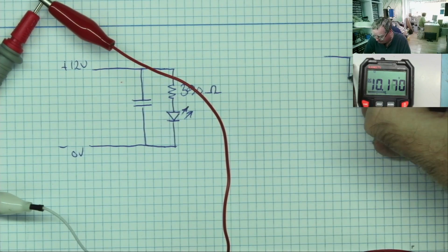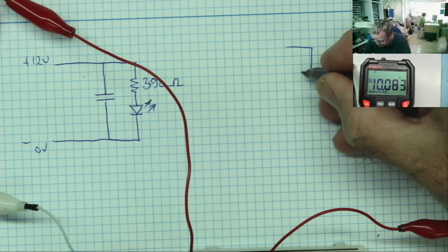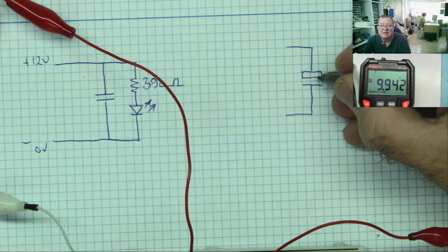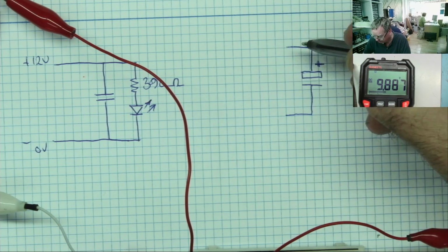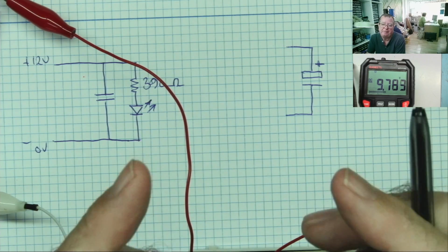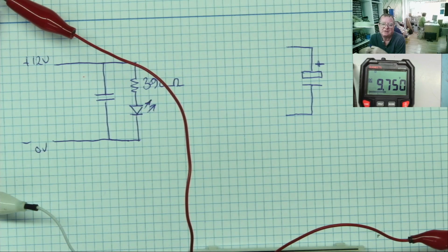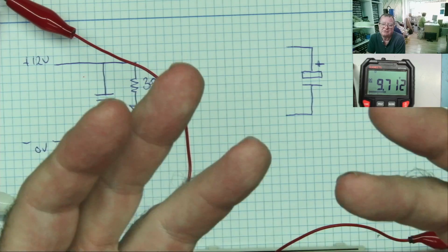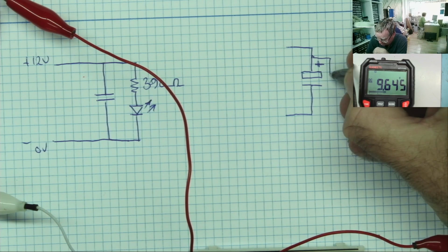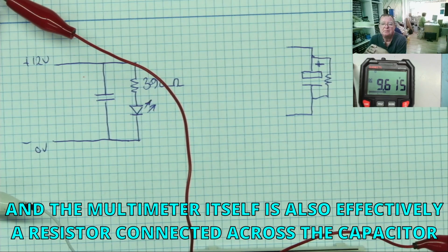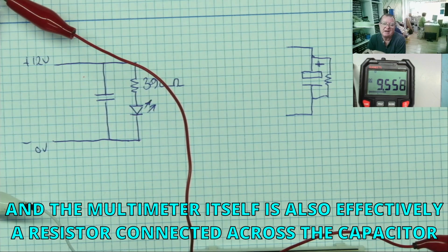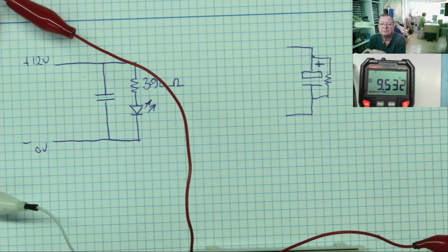With a capacitor, and this is an electrolytic capacitor, which is polarized, by the way, and it has a different symbol. There are a few variants on this, but we'll just use this one. This is the positive end where the wide bar is, okay? Now in between is an insulator, the dielectric, but an insulator is never a perfect insulator, especially with electrolytic capacitors, because this is just a metal oxide film in an electrolytic solution. It has a certain amount of leakage resistance. So effectively there is a resistor inside the capacitor like that. And that's not because somebody put a resistor in the capacitor. This is a byproduct of the manufacturing technique used for these types of capacitors. So it will discharge, but it will take a very long time.